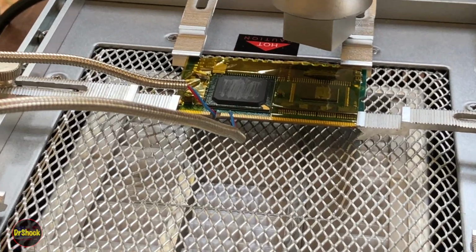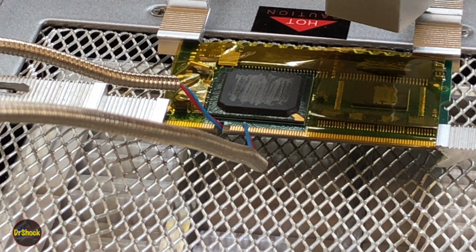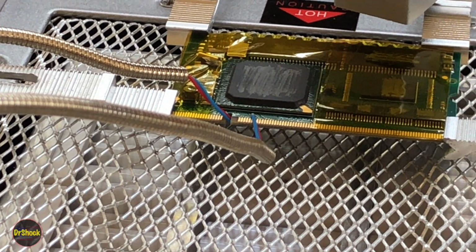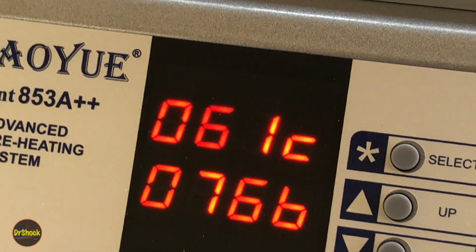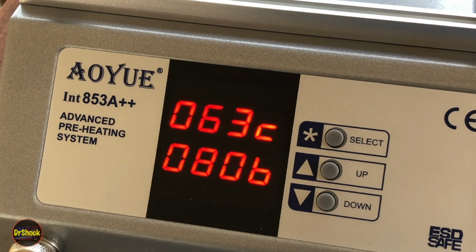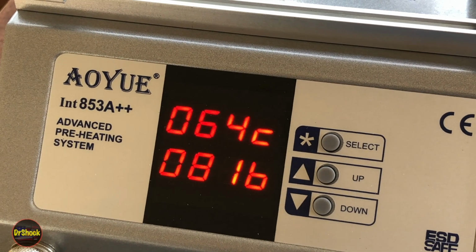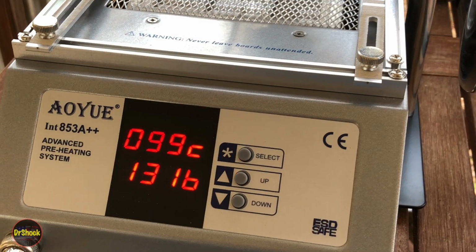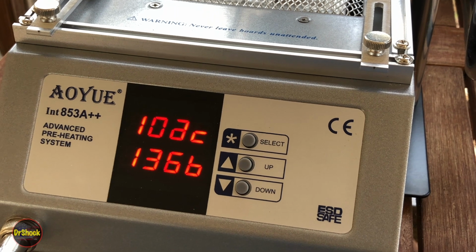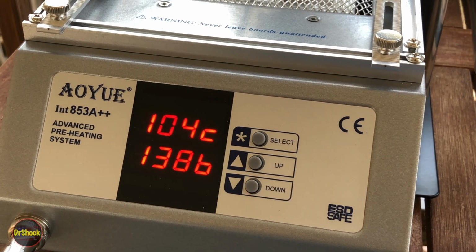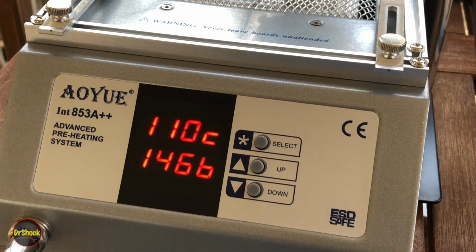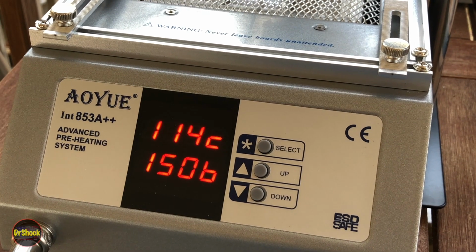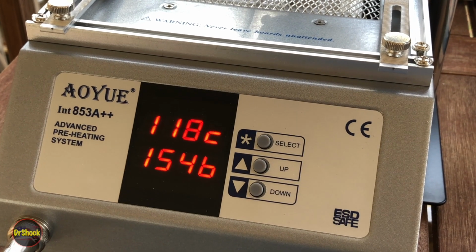All right, so we've got 2 thermocouple probes, one on the top of the board and one underneath the board as close to the device as we can. And then we're just monitoring the top and the bottom temperatures as she heats up, and she's going through this particular curve profile. Just another shot as she's going through this curve. The C is the top probe and the B is the bottom probe. That's just the jargon for this particular product. It's displaying output in Celsius here.